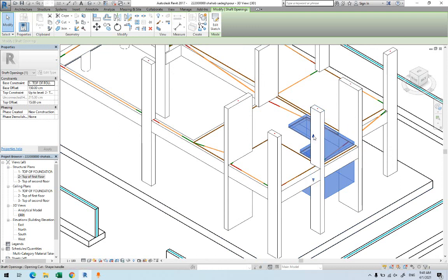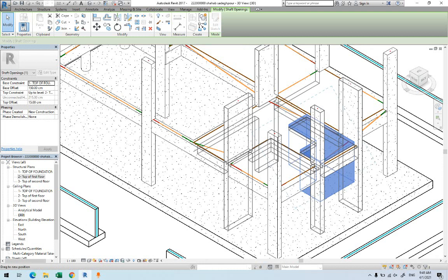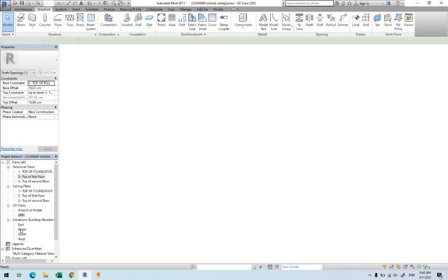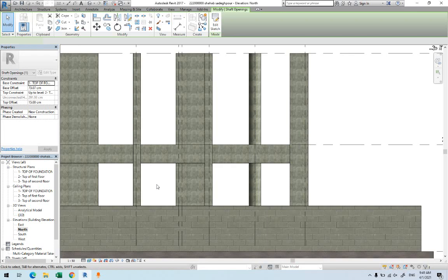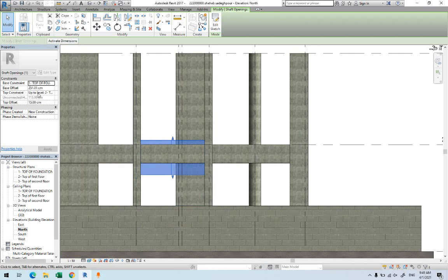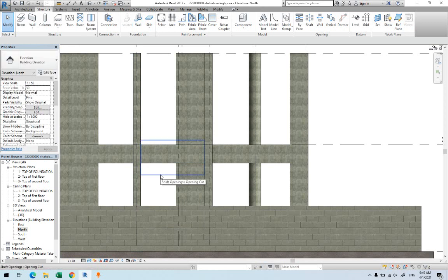So even here you will see two buttons that are basically responsible for what? For the height of this, that you can increase and decrease the height. So this can even be done in the elevations, which will be easier. This is the shaft. We have a look. We'll make sure that it only cuts the slab. I can just bring it back here. Or we can adjust them with what? With the dimensions here. That's also possible. It will not be seen, but it is available as a hidden shaft opening, which cuts the slab we have.